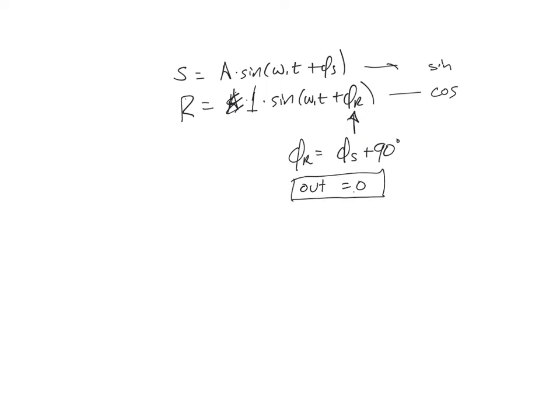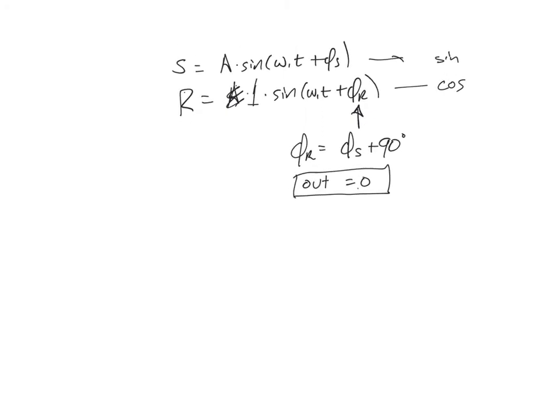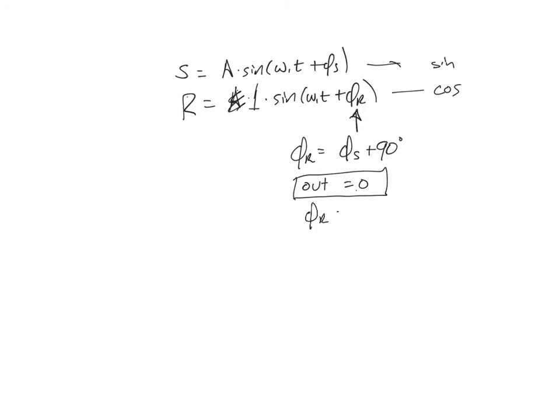If you tune your output phase such that you get 0, if you just go to the right number of degrees such that you get no output, and then you hit a button on the lock-in that says, okay, phi r, I'm going to change it to the current phi r, so phi r prime is equal to the current phi r plus 90 degrees, then that brings you again to the beautiful maximum where these two phases are the same. A more sensitive way of setting the phase adjustment is to first make it so one is sine and the other is cosine, which is to say get 90 degrees out of phase, zero the signal, then hit the button that says switch it by 90 degrees, please, and that'll give you the maximum.